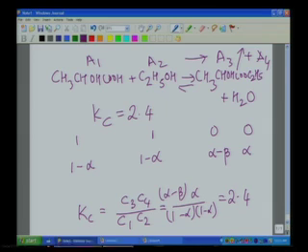If beta is 0, we got our alpha equilibrium as 0.6, but for any non-zero value of beta, and of course we are looking for positive values of beta, you can see that this equation will lead to a solution where alpha E will be greater than 0.6, depending on the value of beta. In other words, we are able to overcome the limitations of thermodynamics by combining reaction with distillation. So, we have reactive distillation, thereby overcoming this limitation.